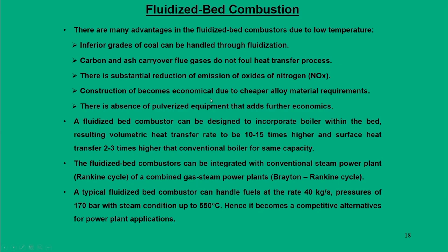There are many advantages of these fluidized bed combustors due to its low temperatures. That means, through this fluidized bed technology, inferior grades of coals can be handled because we are bringing them into a fluidization state. Carbon and ash carryovers in the flue gas do not cause any kind of harmful effect in the heat transfer process, and there is a substantial reduction of emission of oxides of nitrogen, that is NOx reduces drastically.